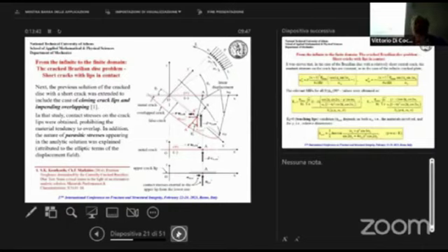Obviously, the next step was to consider contact. Under specific conditions of crack inclination, contact cannot be avoided. Overlapping can, but contact no. Avoiding overlapping, we generate contact stresses. So the challenge was to calculate the contact stresses in this finite domain.